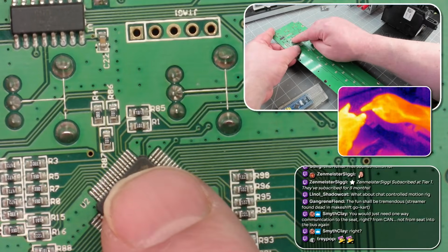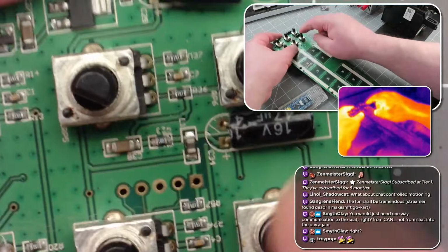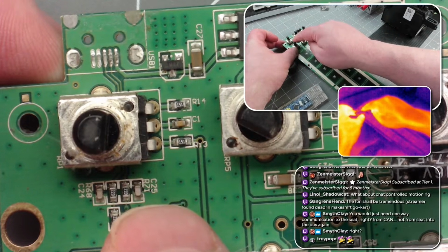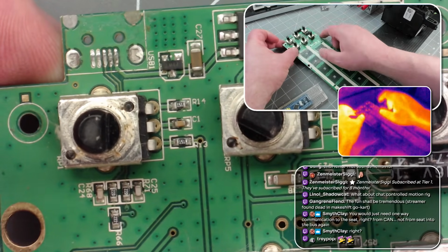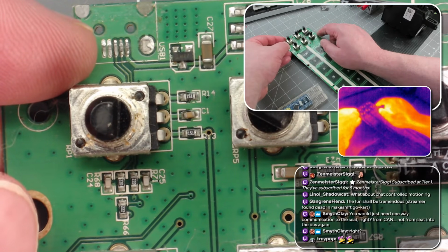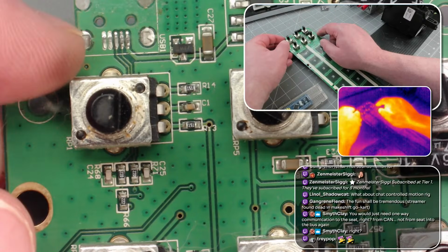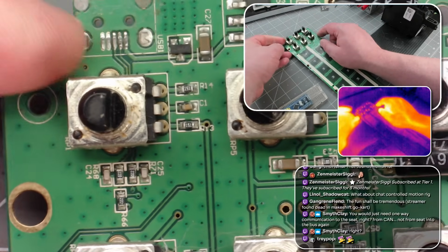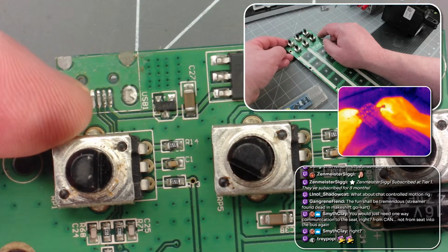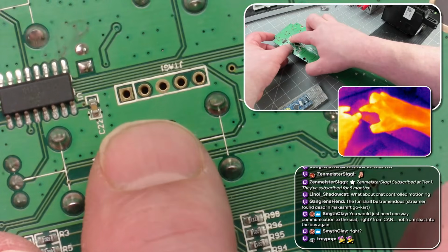The Midi thing has the USB pins, but they go up here, and they go just directly to the USB through some resistors, like some protection resistors. They just go straight out to USB. Those also happen to be the CAN bus pins, so I will be able to hook up our CAN bus board either here or back here, and I will be able to make the output of this thing CAN bus, and I'll maybe put a different 4-pin header over here because we don't really need the USB socket. That's kind of hateful. I don't like that socket. It's not good. But we also have our JTAG pins here.